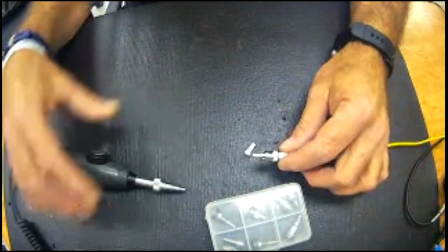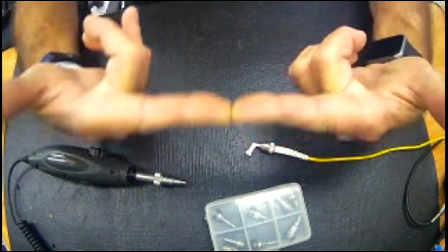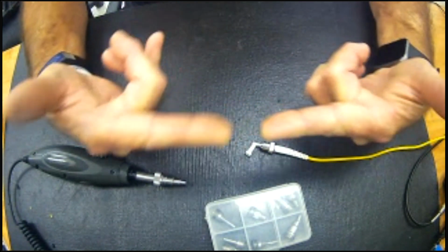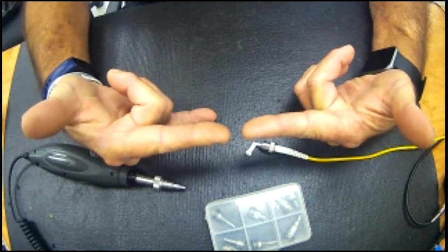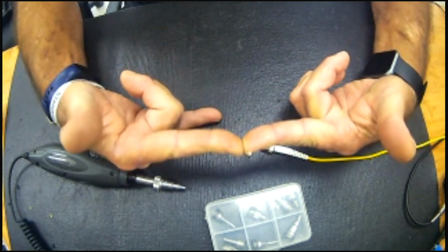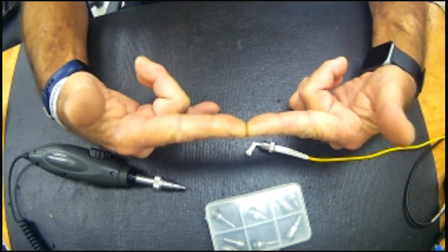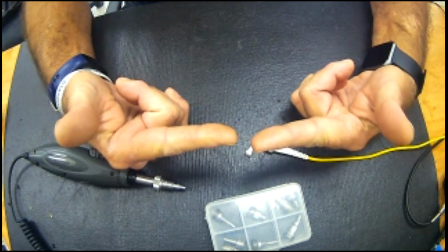So I'm going to switch back to my other one, and it requires 2 steps to get there. Okay. Contacts are always positively engaged. Other than expanded beam, contacts are all mashed together. There's some people out there that always thought that contacts were spaced apart inside of alignment sleeves. That is a fallacy. Alignment sleeves, they are not. They're actually mashed together. So they are 2 contacts that are mashed together under spring-loaded pressure. So anything that's on one is immediately transferred to the other.